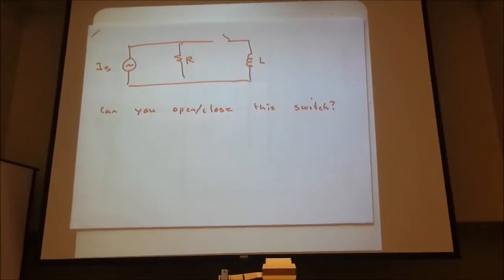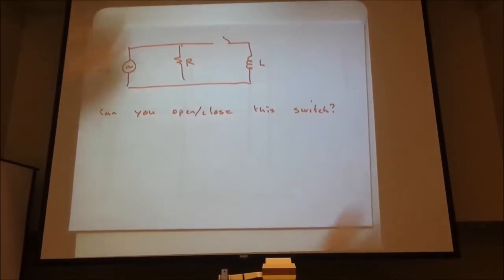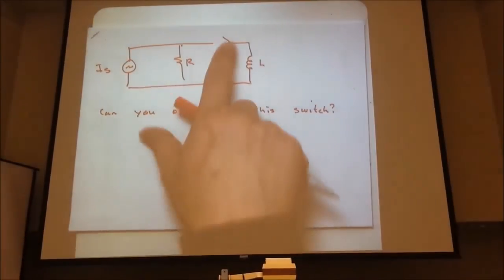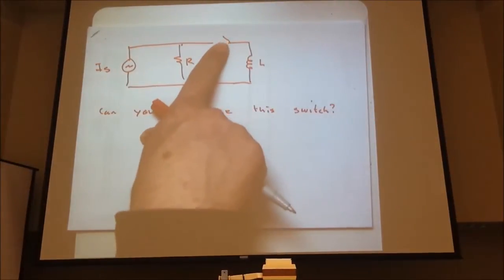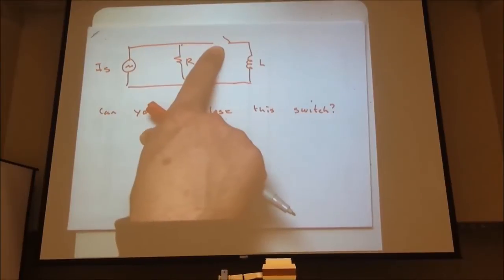How do you open the power system, especially if things are going catastrophic and you really need to shut off power? You need a pneumatic press. You need a very strong mechanical system to force open the switch, because the magnetic field or the current actually keeps trying to pull that switch closed, and it's a lot of energy.